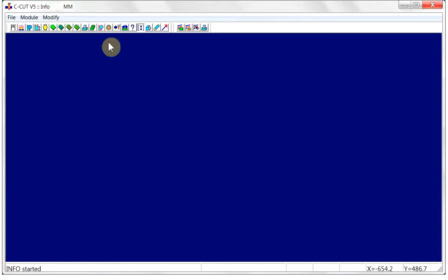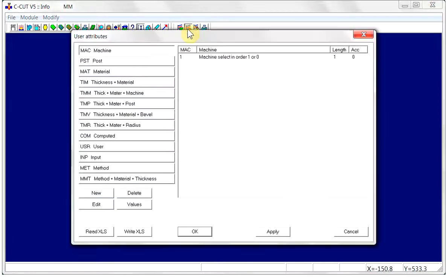We want to disable the height sensor 1/4 of a second before the end of the cut.